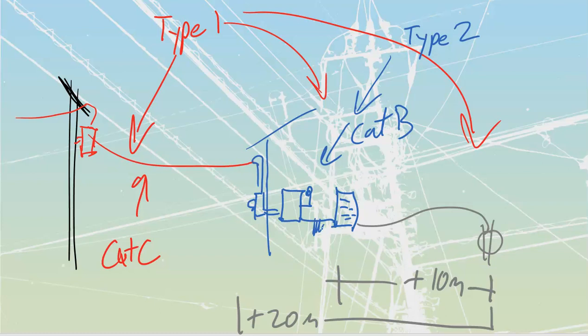They do have a little bit of an errata inside of your binder over here, where it talks about a variant that most homeowners purchase if wanting to have surge protection on an existing residence, or whole home surge protection. They refer to it as a type 3 inside of there. It is going to be a type 2 over there. So inside of that paragraph, just list that thing as a type 2. Usually we just see them mounted. They're going to have a little nipple attached to a chunk of flex, and it gets mounted to the side of the panel like that.